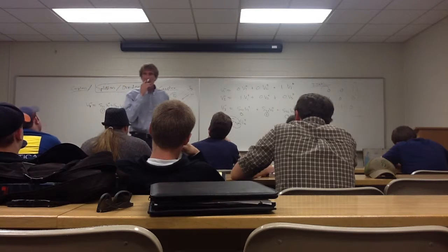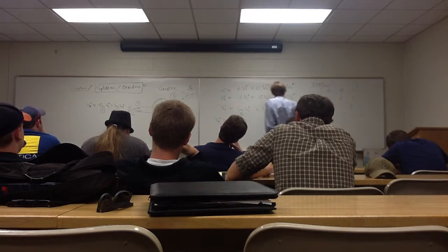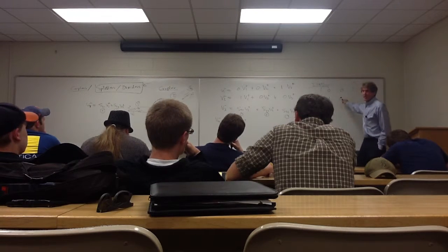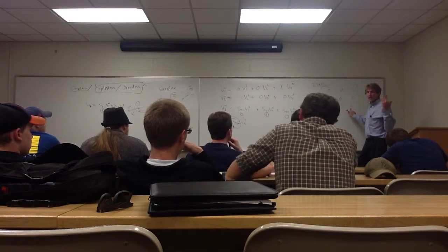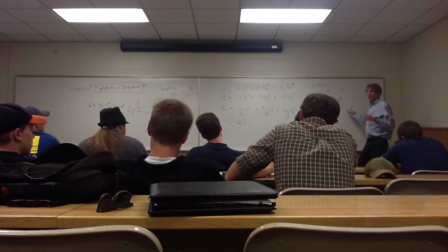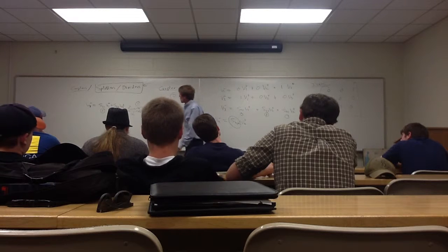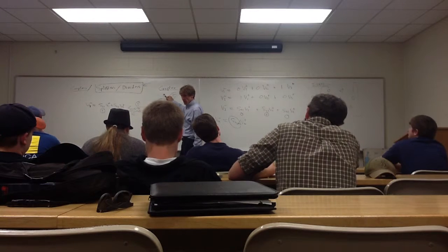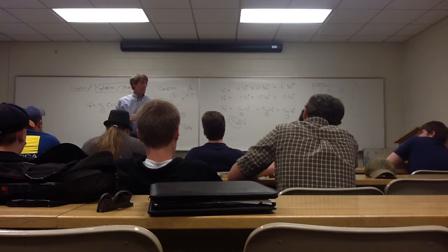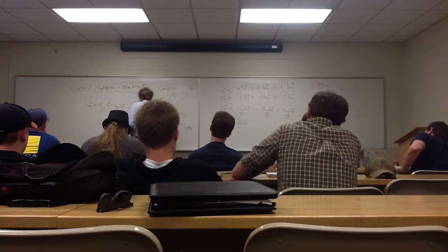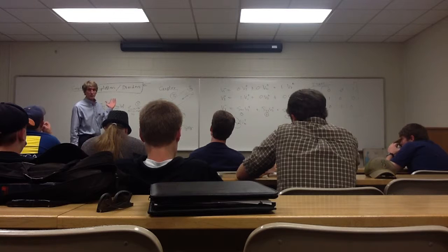It's very easy to do. I'm going to warn you about one thing. You're going to look at some couplers in a second, and all of a sudden you're going to notice that these off-term numbers are not 0. The reason is it's not ideal. Or, in fact, maybe you want a very small amount of signal coming in from one of these ports to come out a different port, not where the main coupling is. There are reasons for all of this, so just remember that. That's the coupler in a nutshell, and it's ideal. It's not hard to do. You try a few, you'll get it, I'm sure.